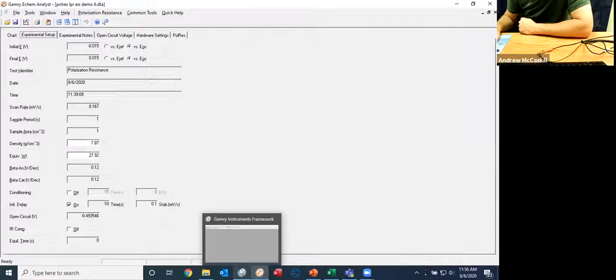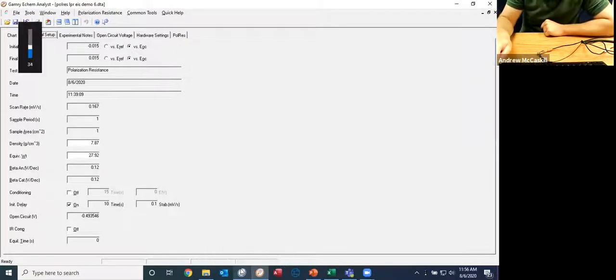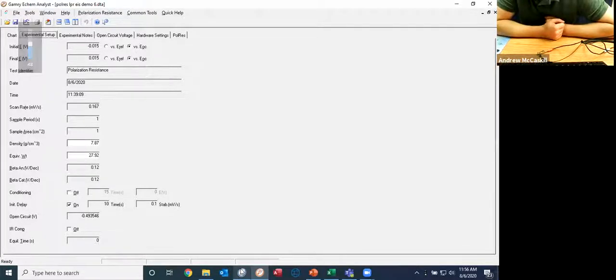We were just right now doing LPR, Andrew. We were doing the same on an Inconel sample at 500 C. It's a high temperature environment that we are doing the test. The OCP is fairly smooth. We only have 10 millivolts change in 60 seconds, but the linear scan has a lot of fluctuation.